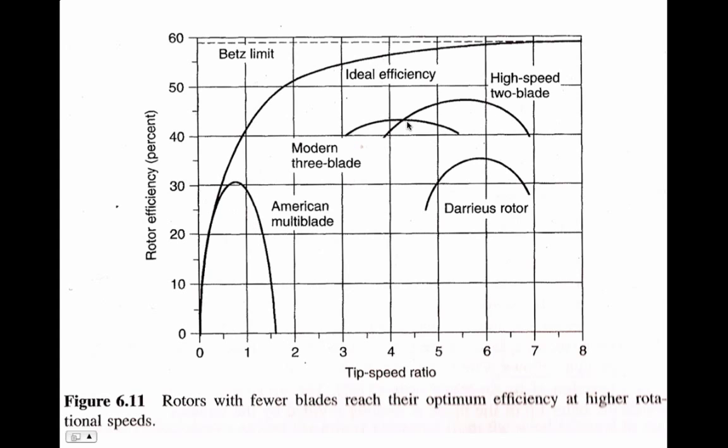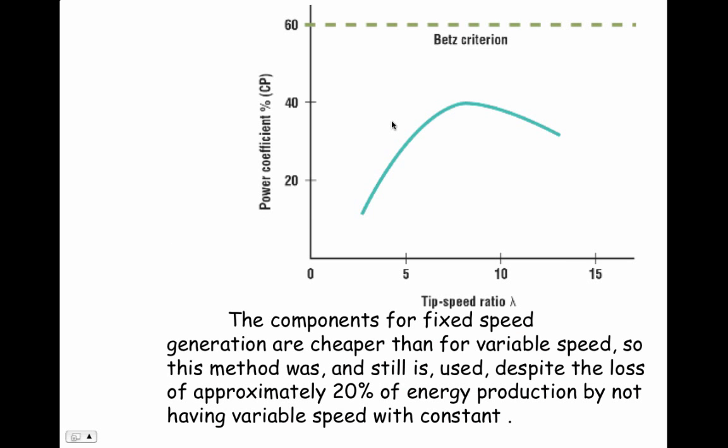So when you have a wind electric generating turbine, that's why you have those two-bladed, three-bladed designs. Again, one blade would be the most efficient, but one blade is very difficult to balance. Two blades are a little easier. With three blades, the mechanical engineering problems in balancing that rotor are much easier to solve than in a two-bladed or a one-bladed one. So even though it's less efficient, it's easier to manage from a mechanical point of view.